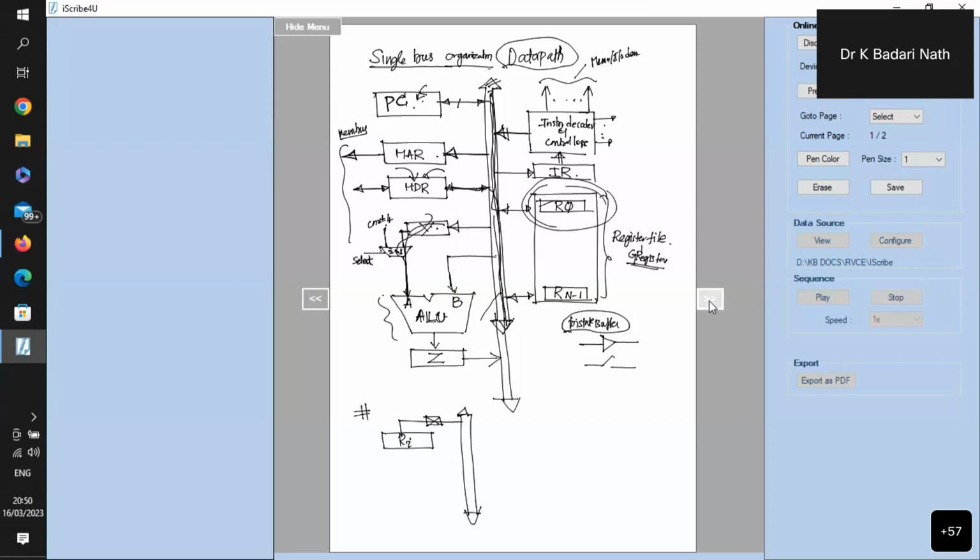All these buffers will have one control signal. Normal inverters have one input and one output. What does a tri-state buffer have? It has one input, one output, and a separate control. Whenever the control is equal to 1, the switch is closed; that is, whatever input you give will be carried to the output. Whenever the control is equal to 0, the switch is open. That means it's physically disconnected.